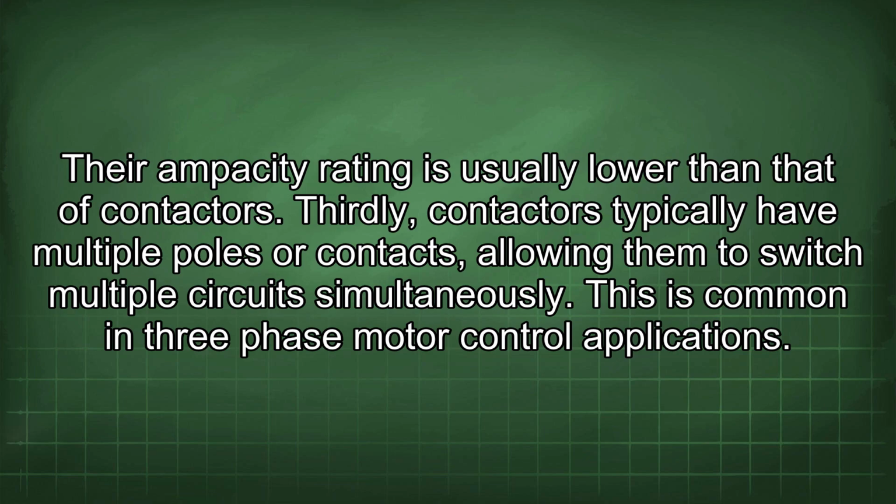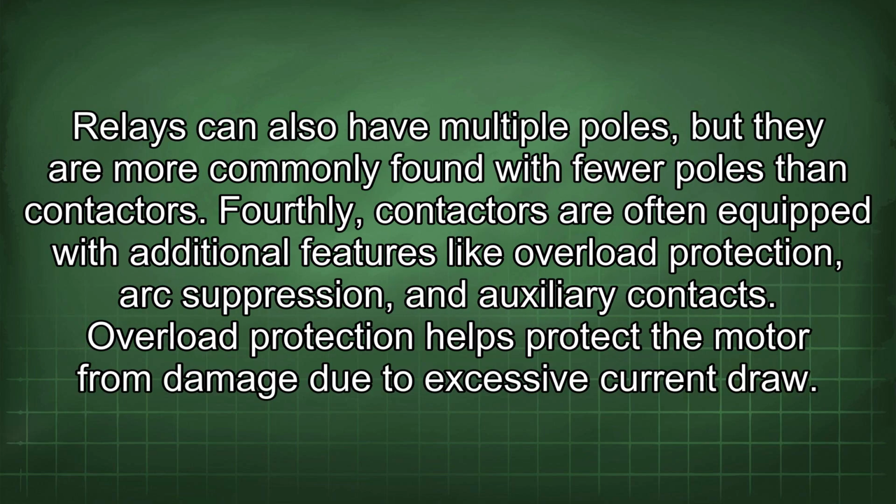Thirdly, contactors typically have multiple poles or contacts, allowing them to switch multiple circuits simultaneously. This is common in three-phase motor control applications. Relays can also have multiple poles, but they are more commonly found with fewer poles than contactors.